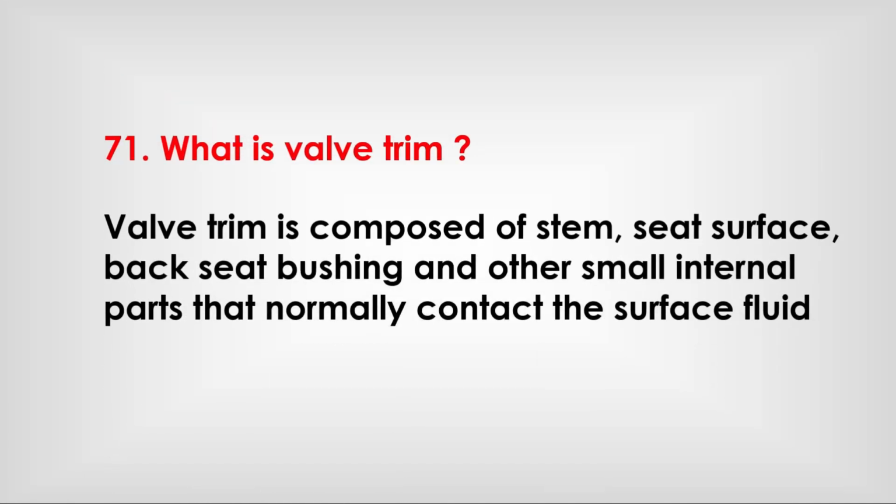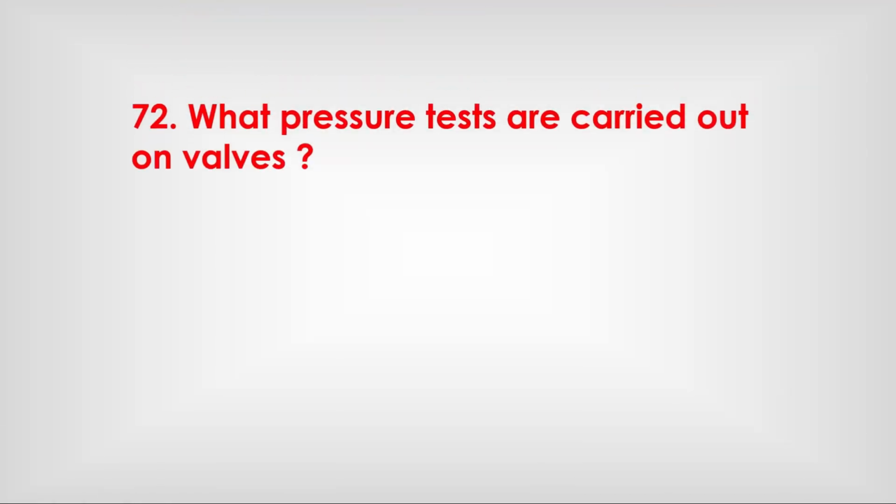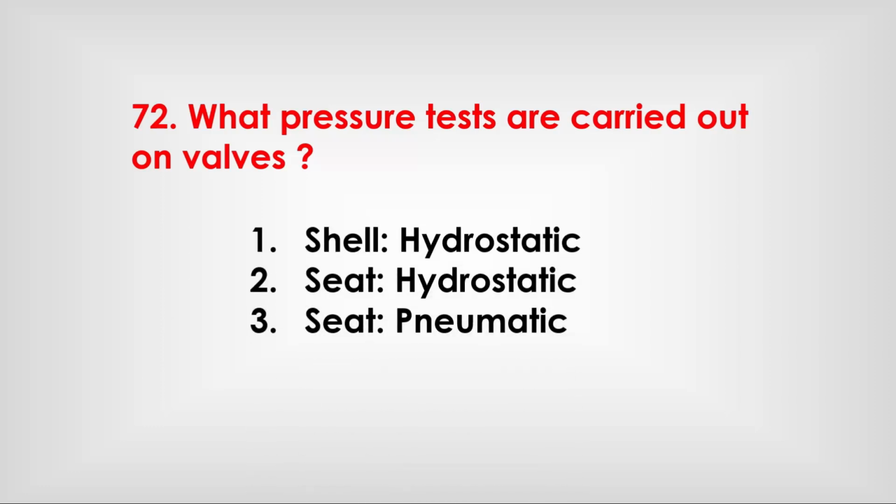What is a valve trim? Valve trim is composed of stem, seat surface, back seat, bushing, and other small internal parts that normally contact the fluid. What pressure tests are carried out on valves? Hydrostatic, seat hydrostatic, seat pneumatic.